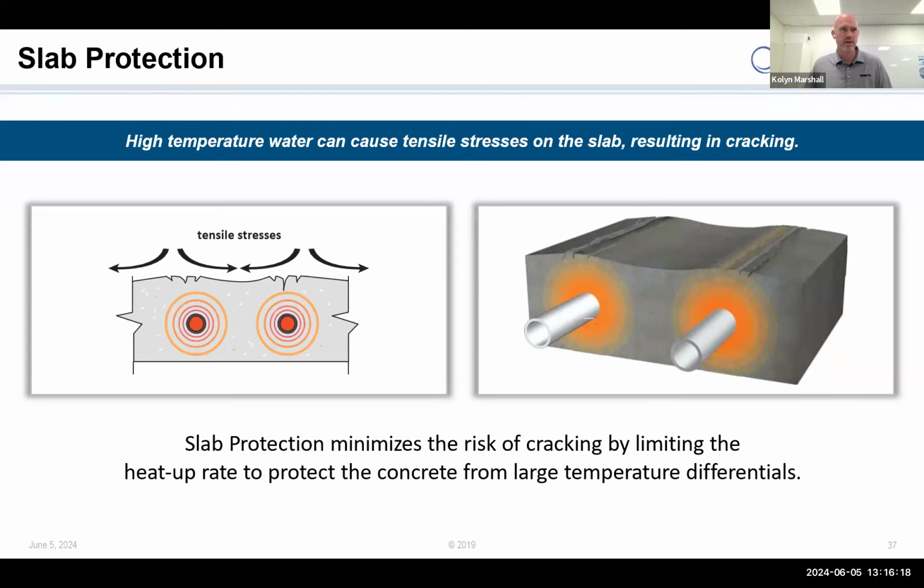But just understand where that rule came from and what's happening dynamically in the system, and know that you have some flexibility. Sand and brick paver systems, I'm not worried about it because I'm in sand. It's a billion cracks already. I'm not going to worry about it. Again, can't shock it. And asphalt, same thing. It's a fluid. It's always moving. You're not going to shock asphalt. Really, the only time that you have to worry about shocking anything is concrete.